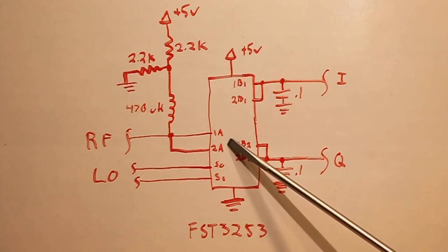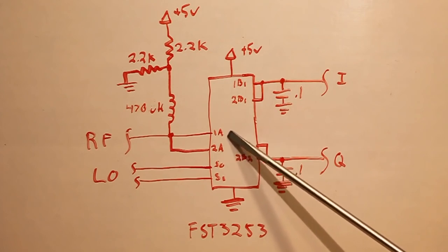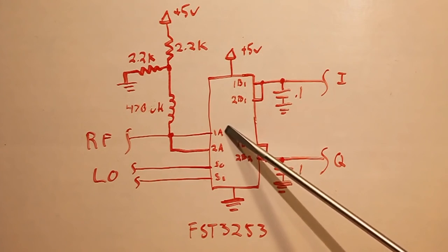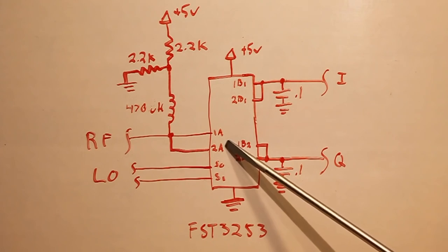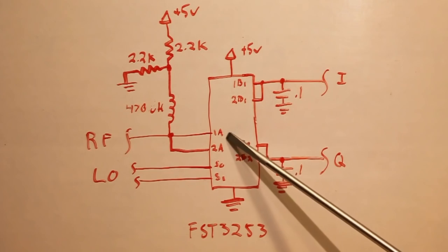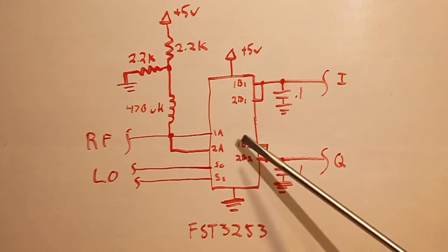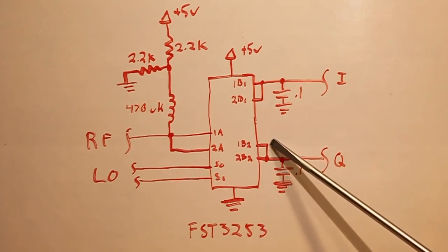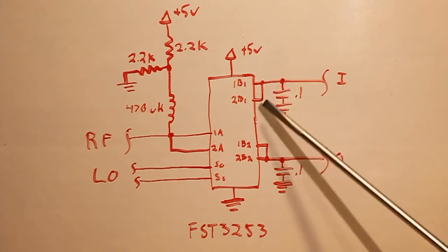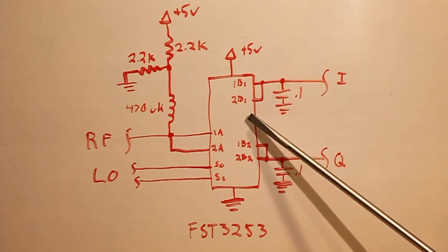And that's really just done to lower the resistance that this chip provides to the signal. So the typical input resistance of each of these is 4 ohms. So if you use both of them in parallel, that drops the total resistance to 2 ohms. And likewise, we can see that the corresponding outputs have been tied together as well from those two internal multiplexers.